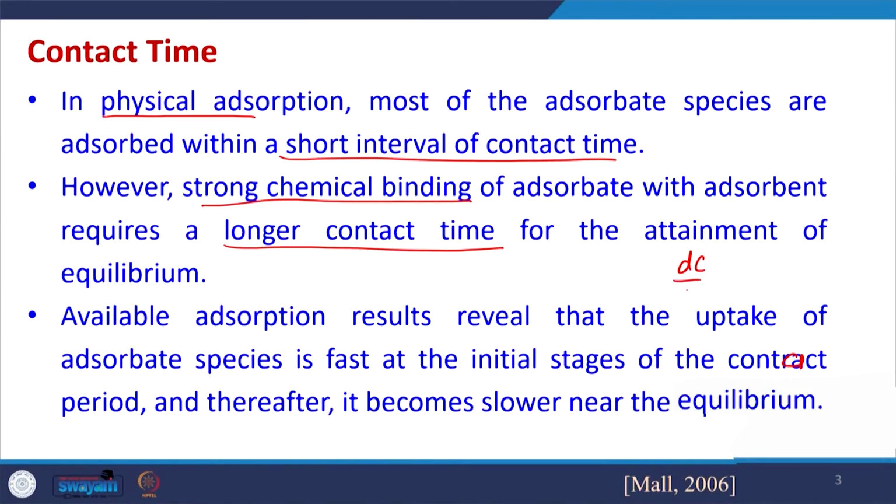We know that the rate of removal of any pollutant, dC by dt, is always proportional to its concentration within the solution. This concentration initially will be very high, so the rate of adsorption is high, and there will be a driving force difference.